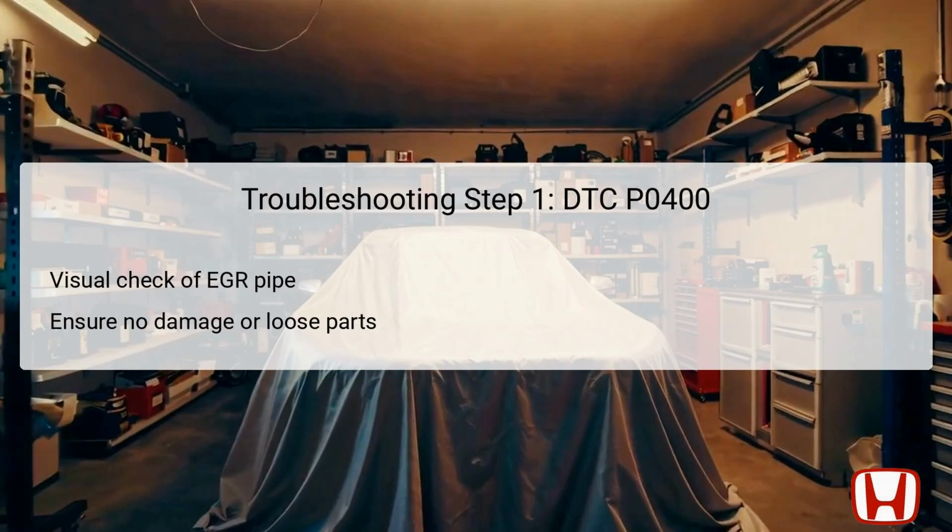If any damage is found, reconnecting or replacing the EGR pipe is necessary before moving forward. This step ensures that the foundation of the EGR system is sound, and tackling these visible issues first can save time later in the troubleshooting process. Always ensure the vehicle is off during this inspection to ensure safety and avoid any potential injuries.